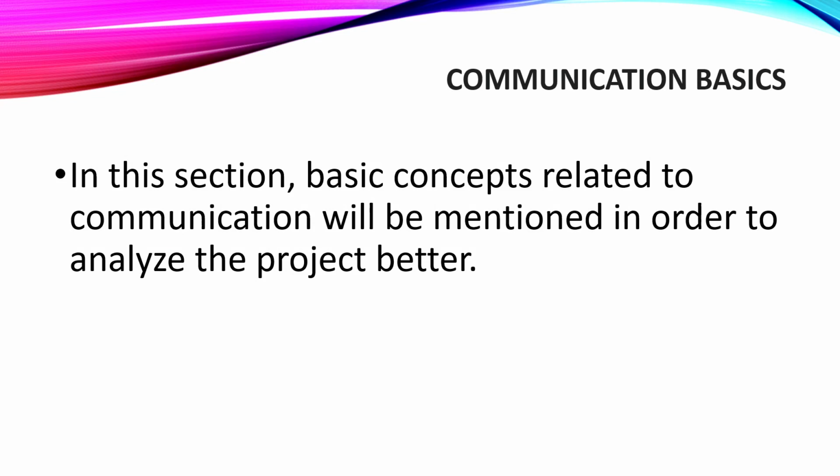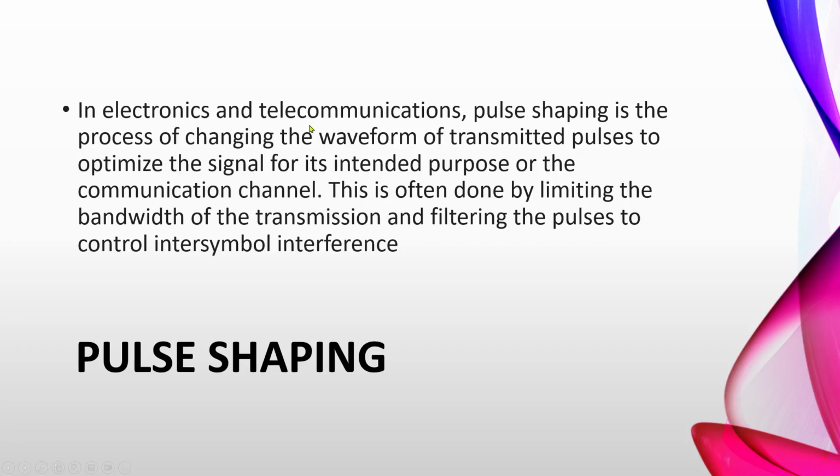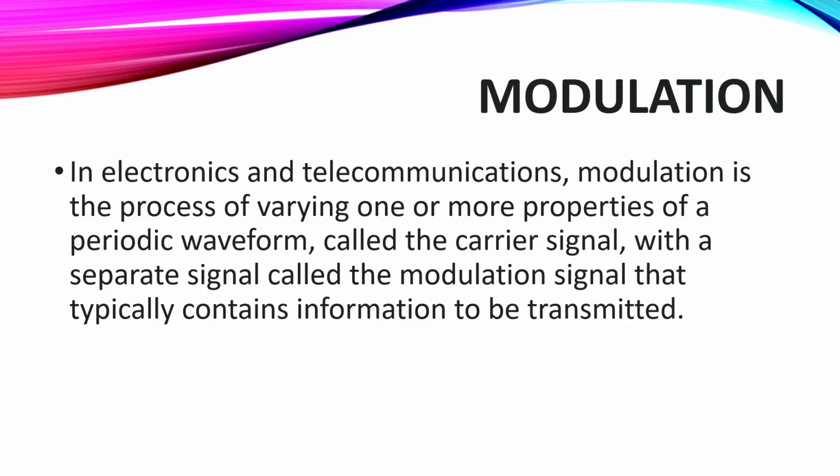In this section, basic concepts related to communication will be mentioned in order to help analyze the project for those who do not understand the communication basics. So, pulse shaping: we chose Manchester pulse shaping, as you remember. What is pulse shaping? In electronics and telecommunications, pulse shaping is the process of changing the waveform of transmitted pulses to optimize the signal for its intended purpose or the communication channel. This is often done by limiting the bandwidth of the transmission and filtering the pulse to control intersymbol interference.